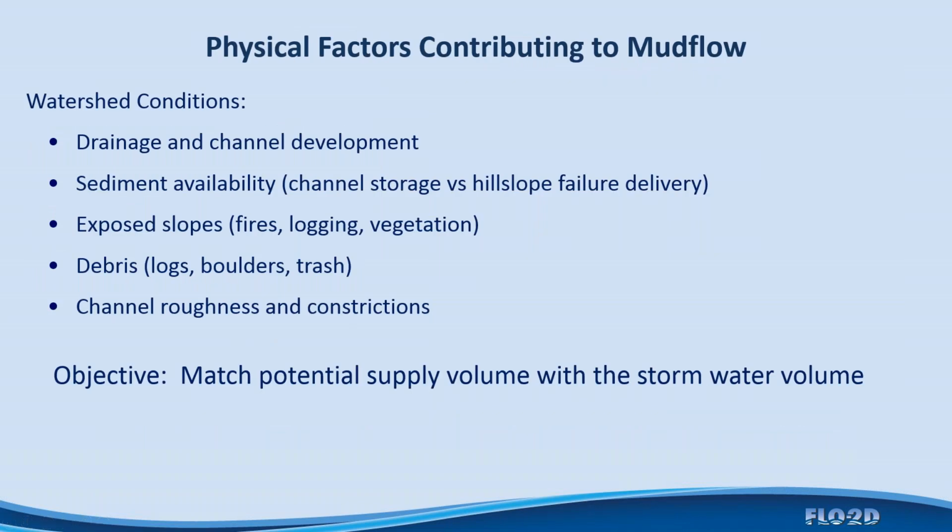Okay, let's talk for a minute about physical factors that lead to the development of a mudflow in a hydrologic condition, meaning that it's generated from a rainstorm or as a flood event. In all of these cases, the objective is, and this is a very interesting proposition, because I like doing this, it gives you the opportunity to match the potential sediment supply with what the model is predicting in terms of both the water volume and the sediment volume to get the total bulk volume of your mud or mudflow or mud flood.